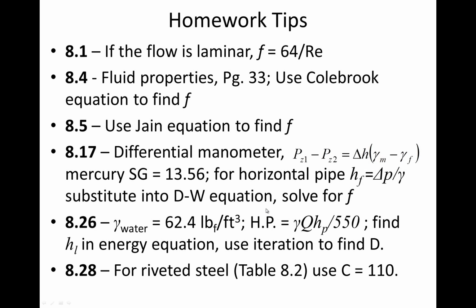So in this problem, if they tell you the horsepower available, you'll know the unit weight and the flow rate. You can find out how much pump head is being added to the system, so that then you can find the head loss in the energy equation.